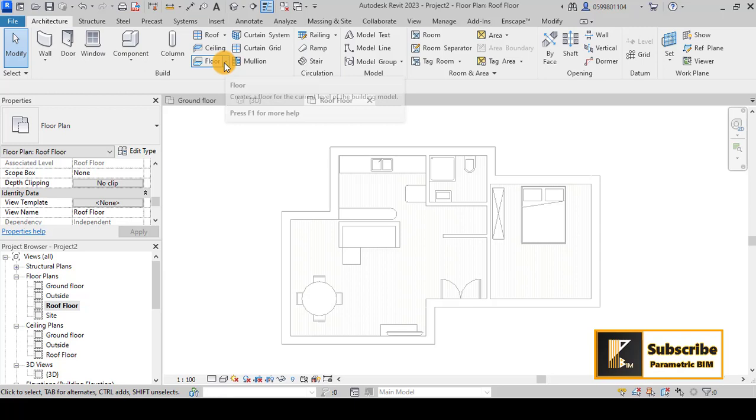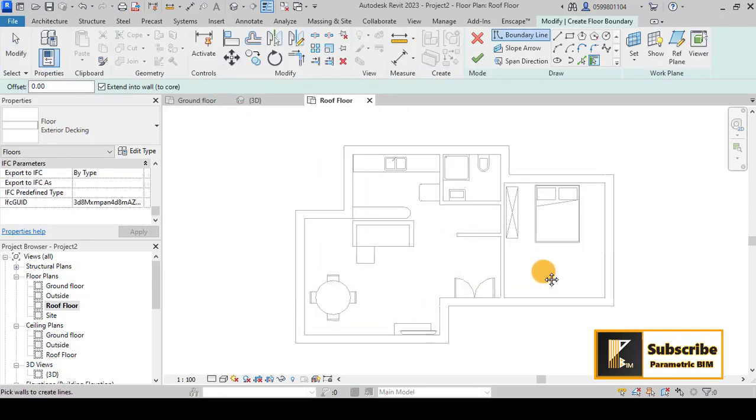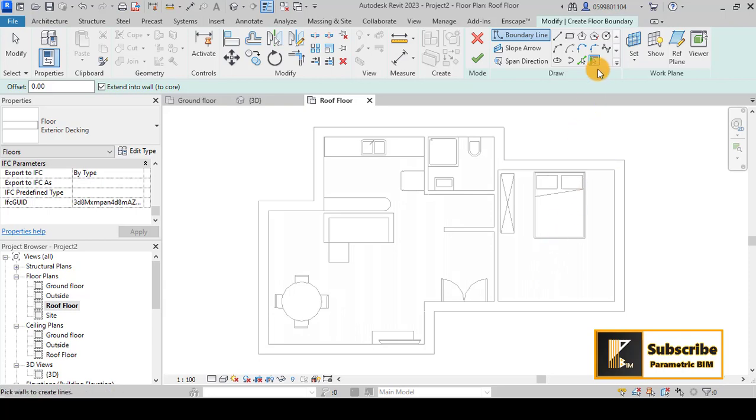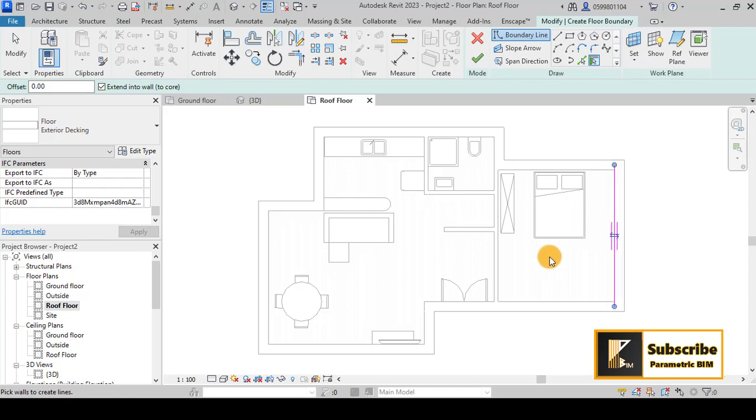But I will go now in this tutorial to architectural floor. And now this is important that you have to choose the big wall, because we have also the walls with the structural and the finishes. So I will choose these walls, but also you can see here that we have an important issue, which is extend into wall to core.